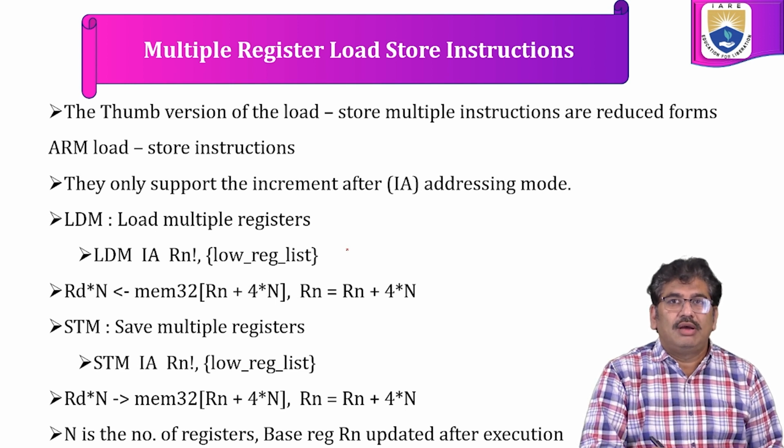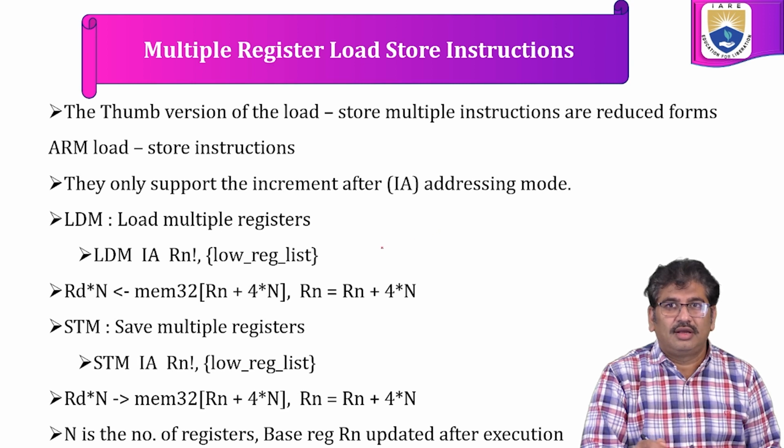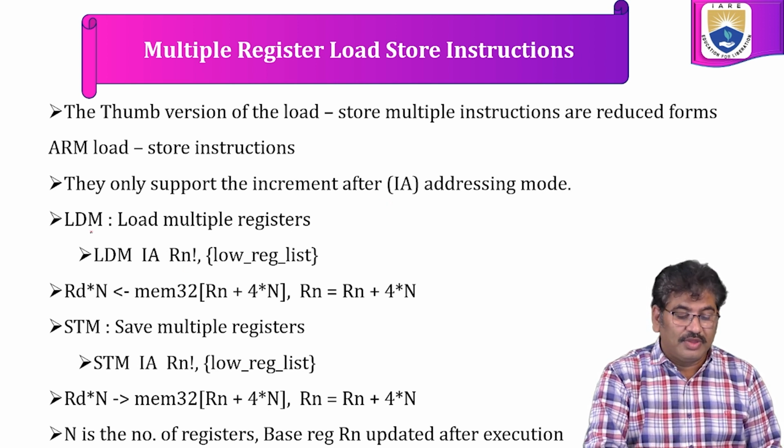The next one is multiple register load store instruction. The Thumb version of load store multiple locations are reduced from ARM load store instructions. They only support increment after addressing mode. Pre-indexing is not supported here. It supports increment after addressing mode only.